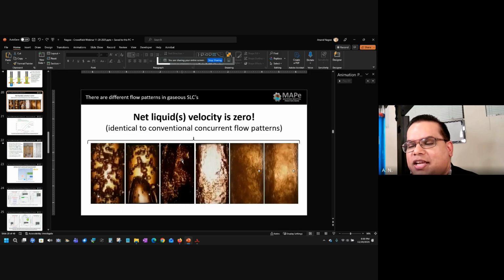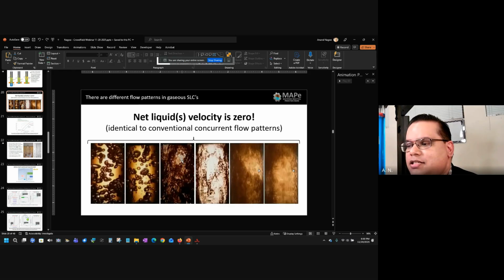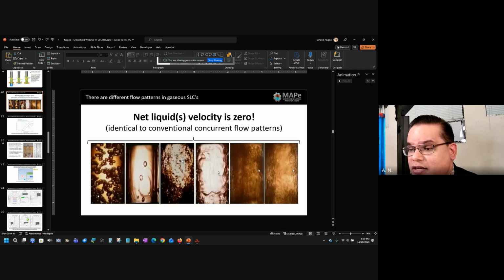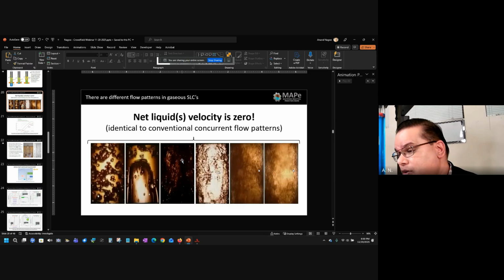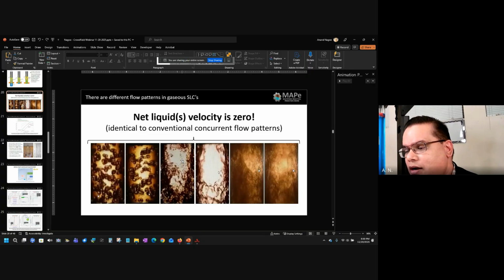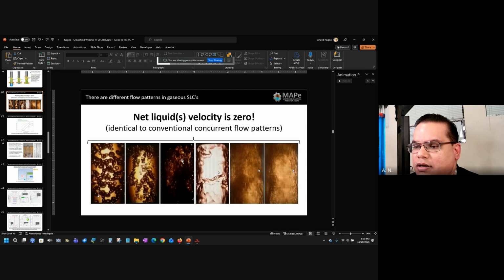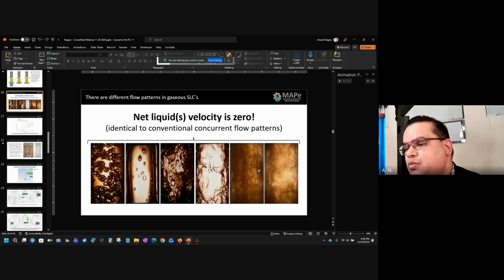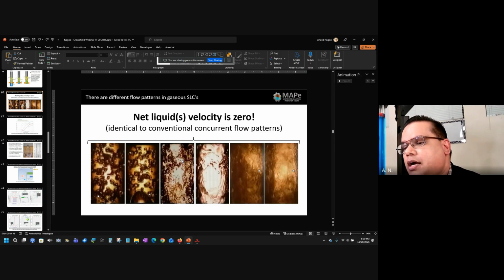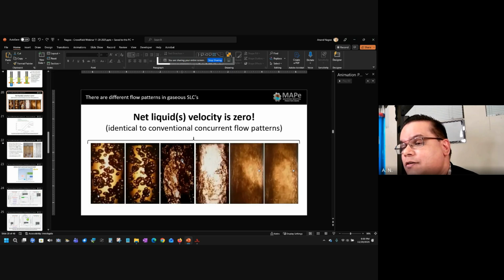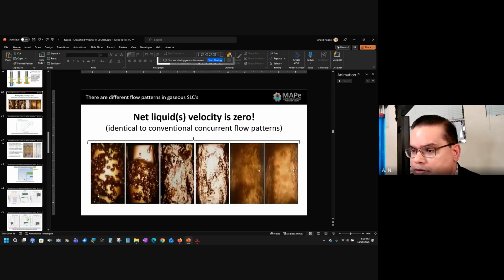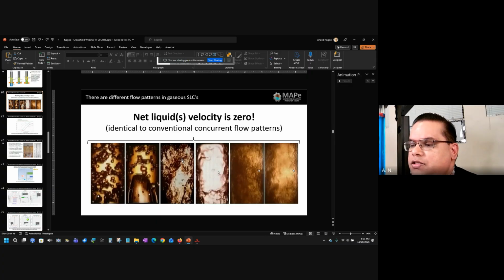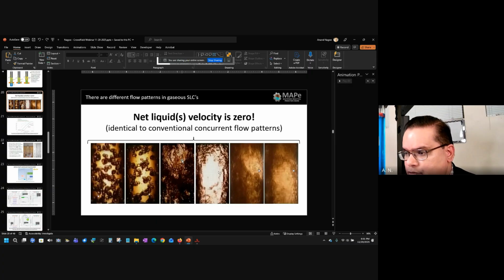So yes, we have been optimizing on plungers based on cycles, based on production, based on different things, but there is the opportunity to optimize plungers based on liquid levels, right? So if we understand our liquid levels in our plunger systems and where our plungers are in those systems, first of all, quantifying the liquid levels in those plunger systems, matching those things with the global macroscopic rate, right? If we understand how they're forming, especially in the afterflow period. So the timing, right? The timing is critical. Those are opportunities for improvement of plunger timing optimization, right?